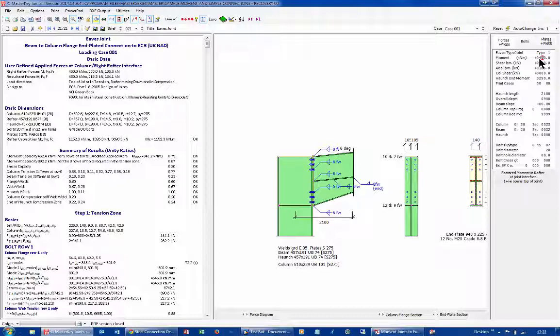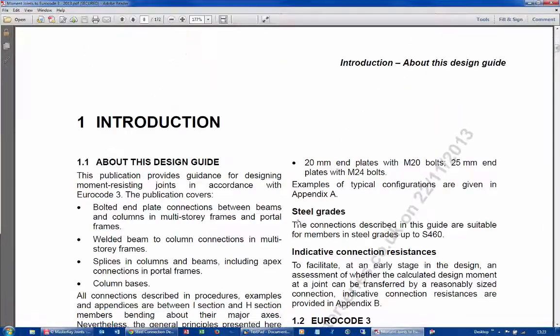So now let's look at what has been designed. So what are the real differences? Well, really, when we're looking at this Eaves connection, which is one of the principal connections in the Green Book on connections to EuroCode, we will see that we actually have modes that are different for PL1 and PL2, for effective length 1 and effective length 2. And the reason for that is that we use, and I'm just going to pop up my publication and come on down to the right page, and yes, this is a legitimate registered copy.